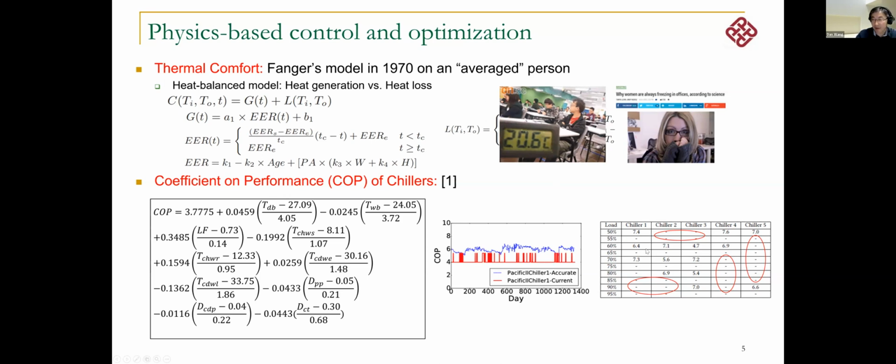In addition to this, usually chillers at the time of installation go through a testing period to configure lots and lots of parameters. But during this test time, many configurations and parameters are still not tested. And if they are not configured, they won't be used. So all of these rule-based controls lead to very coarse-grained control, and that introduces a lot of waste.